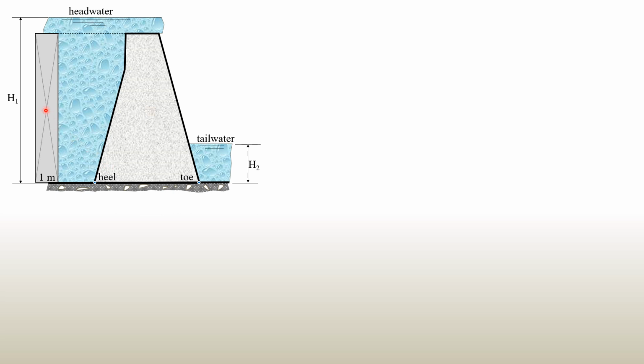And the centroid of this projection is here, so the force FH1 would be below as shown. The distance of the centroid to the water surface in the headwater is denoted by h bar. Then the distance of FH1 from G, just like in plane surfaces, is denoted by e. On the other face, we have FH2 on the tailwater. Of course, if this is the tailwater and it intersects the body of the dam, then this is 2/3 of h2, so there's no need to solve for e.